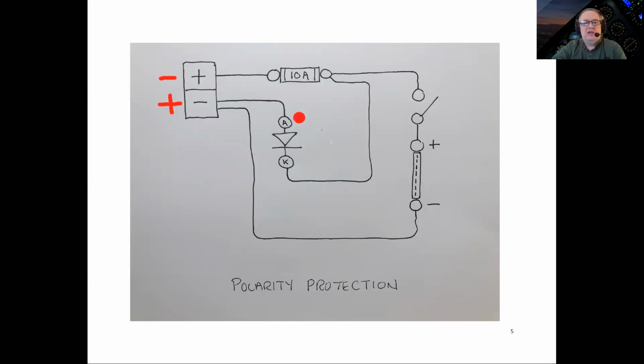The anode would become positive to a positive potential. Now that's forward biased, so we would have flow through the diode immediately up to this point right here at the fuse, and a direct shot back to the negative terminal, which means current flowing through the fuse, fault current, like short circuit level current, and immediately actually blowing the fuse.